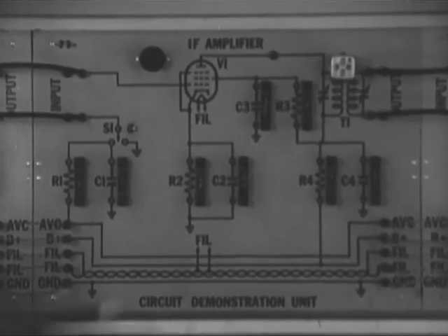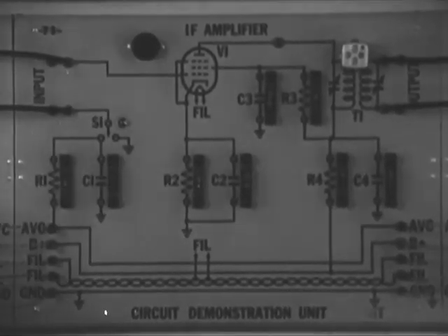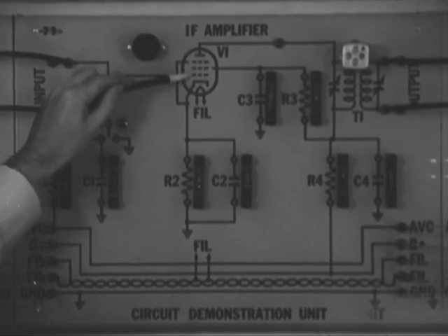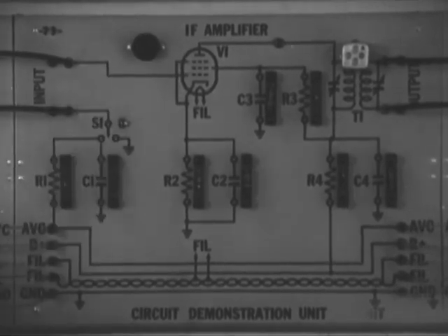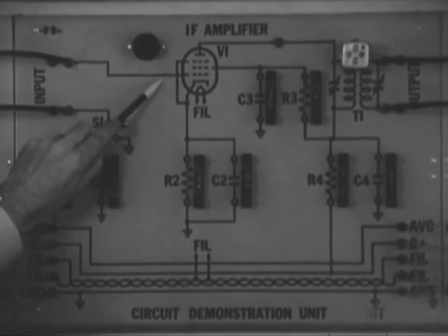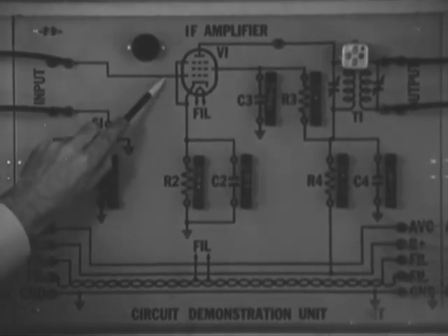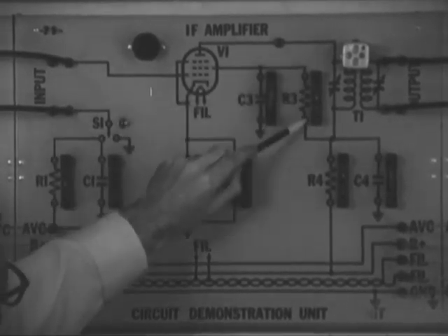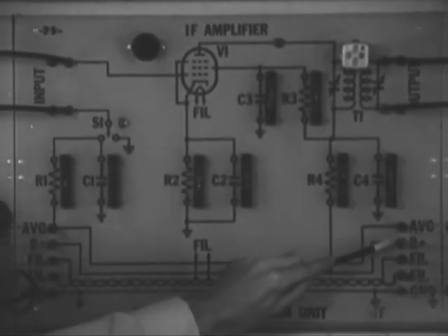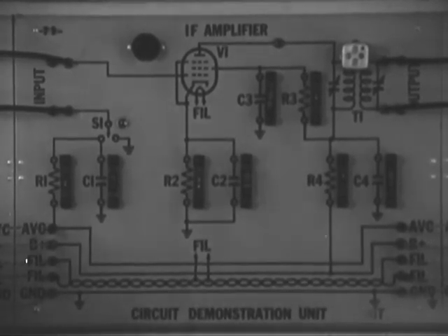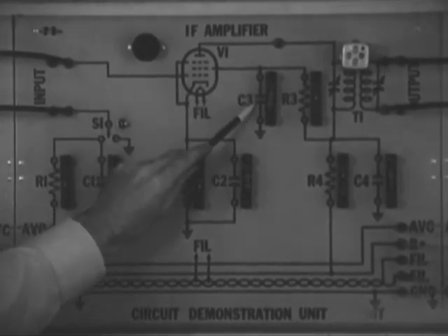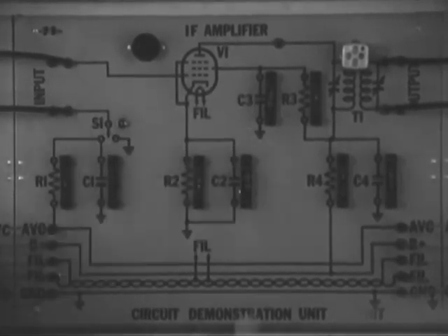A pentode is used because it has a much higher amplification factor than the simpler triode. A pentode has 5 active elements: the cathode, plate, and 3 grids. Grid number 1 is the control grid and is similar to the grid in a triode. Grid number 2 is called a screen grid and must be connected to high positive voltage. Current flows in the screen grid, and any signal which develops on it is shunted to ground with this bypass capacitor. Grid number 3 is called a suppressor grid and is connected to the cathode.